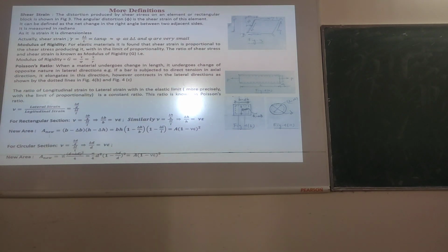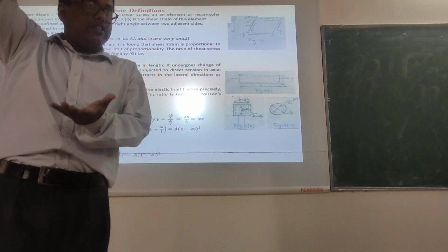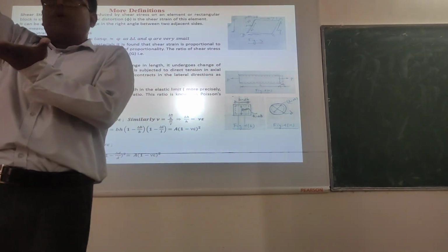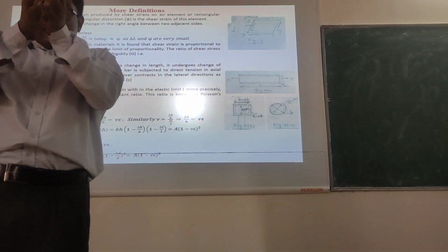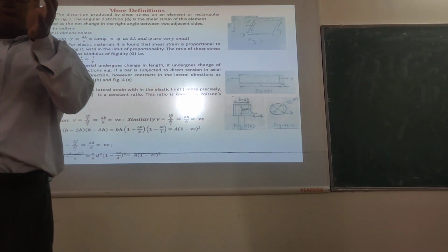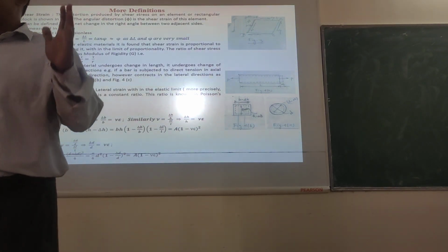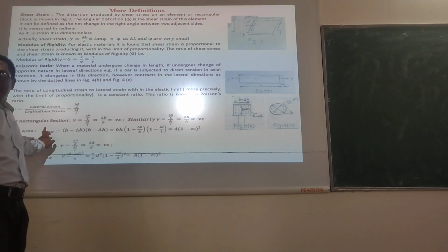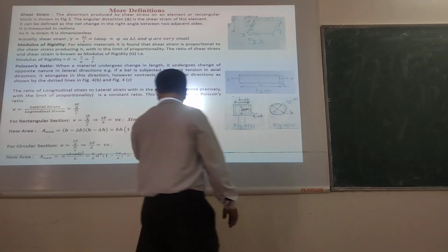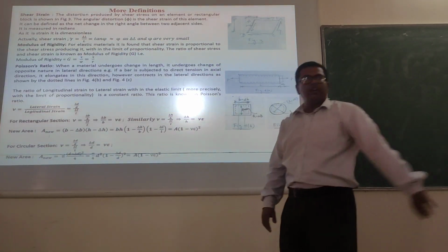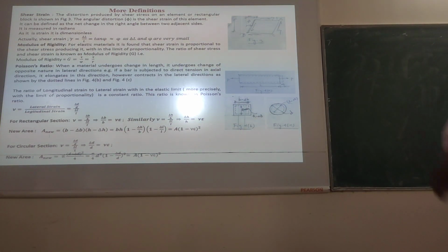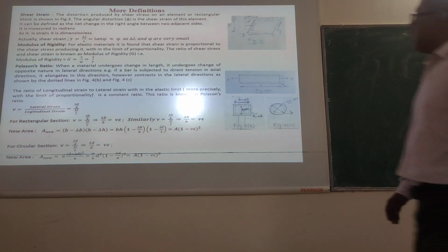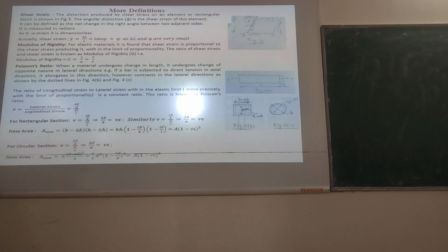When you will be studying the shear strength of soil, and when there is compression in a direct compression test, there will be shortening of the body in one direction and expansion of the body in the other direction. So when you are calculating the stress, in many cases you have to calculate the stress in terms of this A nu, and this A nu you can obtain using A into (1 minus mu epsilon) squared. Got it? Clear? So next slide, let's move to the next part.